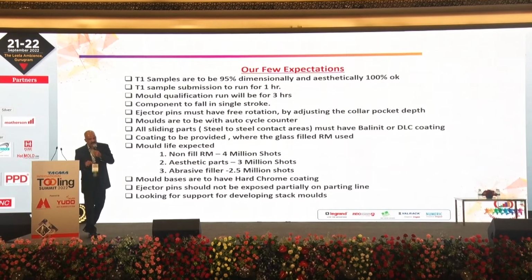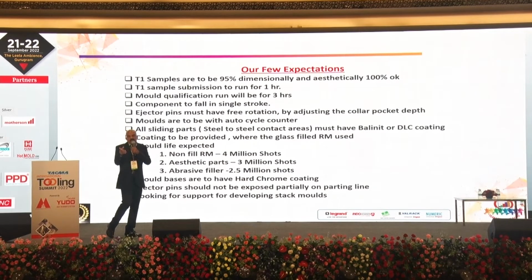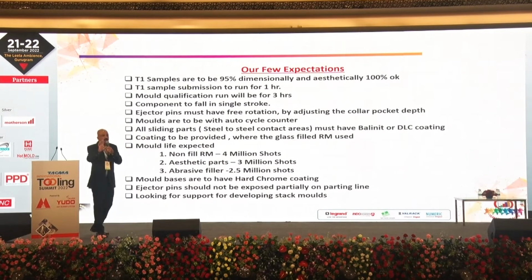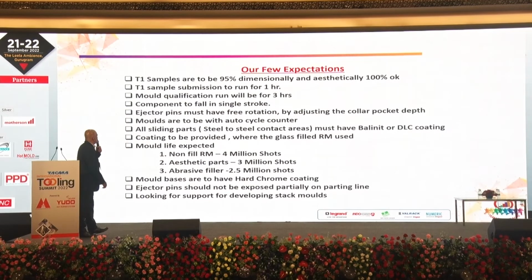Note down the problems you are getting. Ask the supplier to correct it, ask the mold maker to correct it. Maybe in 2 months' time you will get the feedback, and in 2 months' time you should be able to ship the mold. Mold qualification run will be 3 hours for buy-off trials.